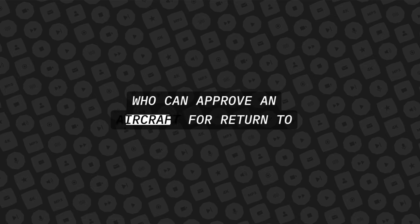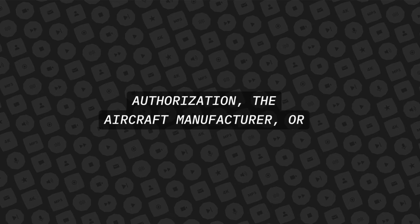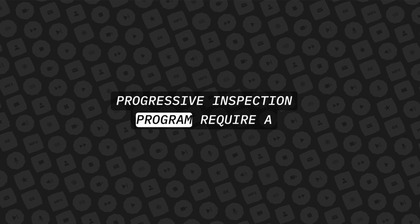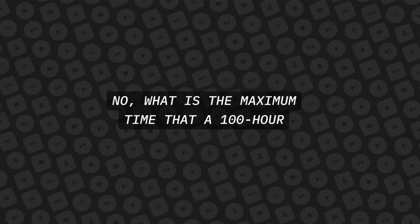Who can approve an aircraft for return to service after a progressive inspection has been performed? A certified mechanic holding an inspection authorization, the aircraft manufacturer, or a certified repair station. Does an aircraft being operated under a progressive inspection program require a 100-hour inspection if it is used to give flight instruction for hire? No. What is the maximum time that a 100-hour inspection may be extended?